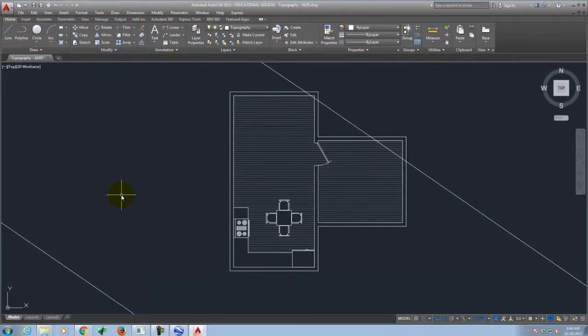That helps it blend into the background so that you have a depth of detail when you look at it this close. But if you hold it further away, you don't necessarily see those lines. That's one of the advantages of using line weights. Now maybe I want to add line weights to my walls. I can select the walls and again come over here to add line weights. And maybe, what did I suggest here? 0.40. So we'll come down here to 0.40, and those are now there.